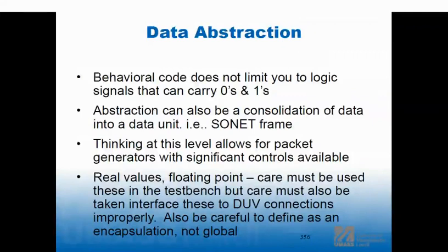But reality is also full of missing bits. So one thing that you might do in a signal processing system is randomly set the data to 0, set it to the highest point for 8 samples in a row or something like that, or a variable number, and see what happens, right? Some of these frame-based FFT things go crazy with just a few bits missing out of the frame that goes into them. So digital signal processing is harder for the type of thing we're doing, because ultimately you're not modeling something digital, right? You're modeling an analog system.